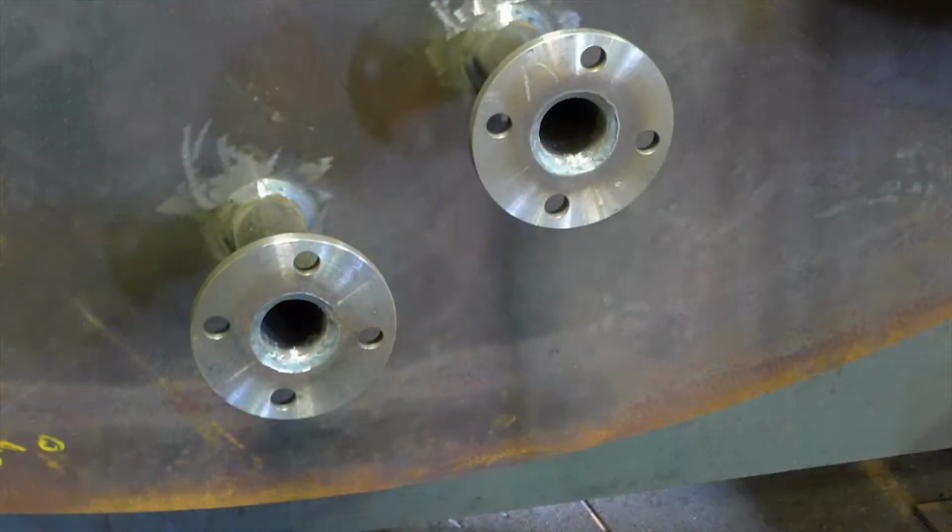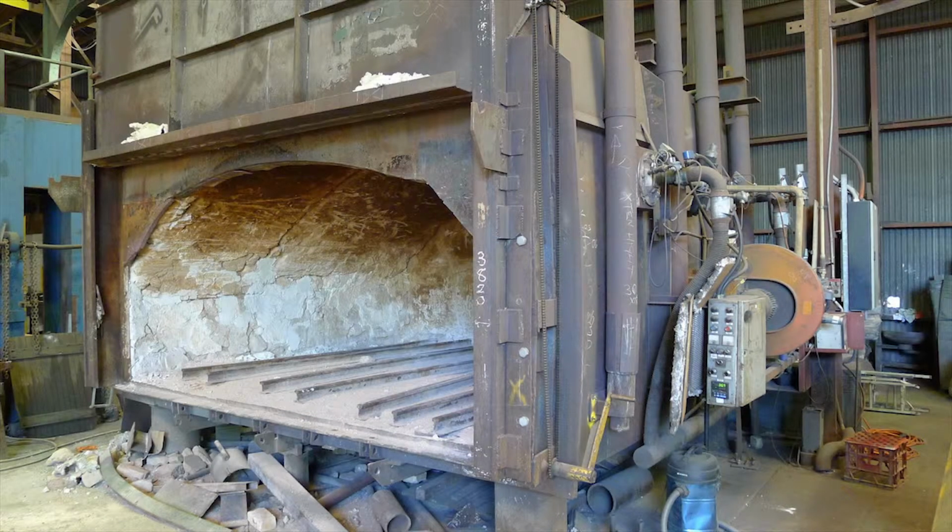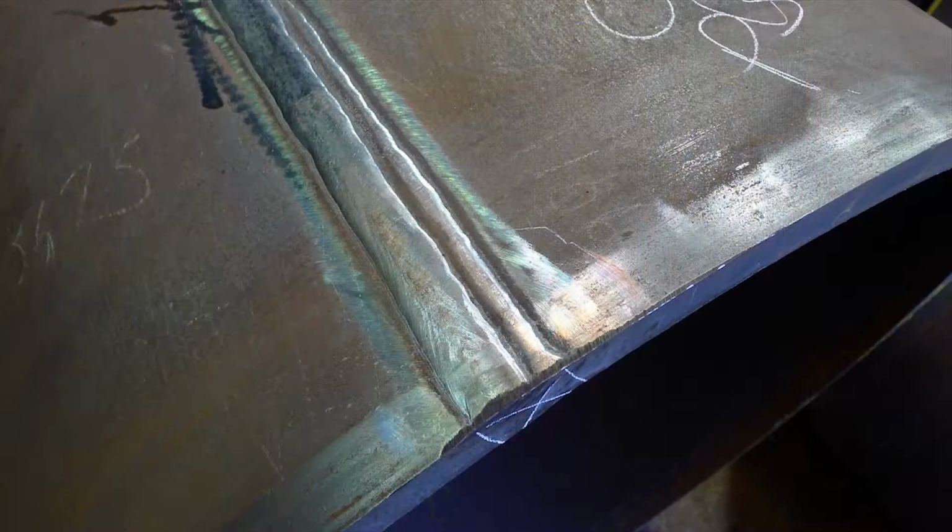ER Curtin does not extensively finish their products on site apart from grinding excess weld material, but they do have a furnace that they use for stress relieving, which is an important finishing process, as well as a furnace for quenching, normalising and annealing, with 1220mm width and 1524mm depth.